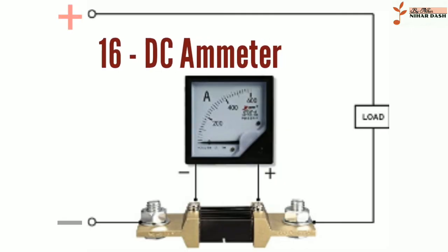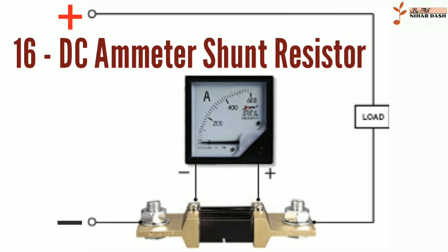16. Ammeter shunts. A resistor ammeter shunt is a special type of current sensing resistor, having 4 terminals and a value in milliohms or even microohms. Current measuring instruments, by themselves, can usually accept only limited currents. To measure high currents, the current passes through the shunt, across which the voltage drop is measured and interpreted as current.